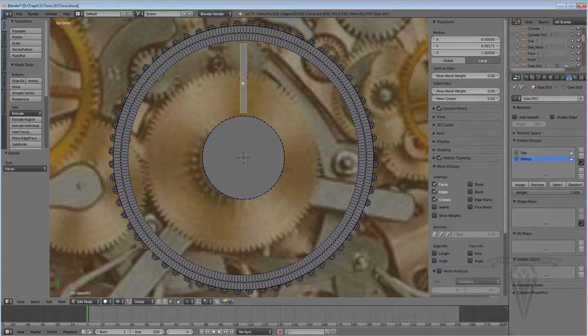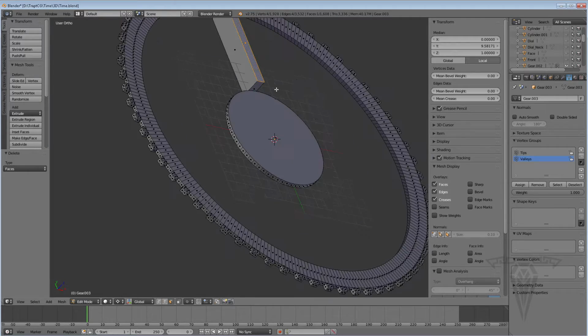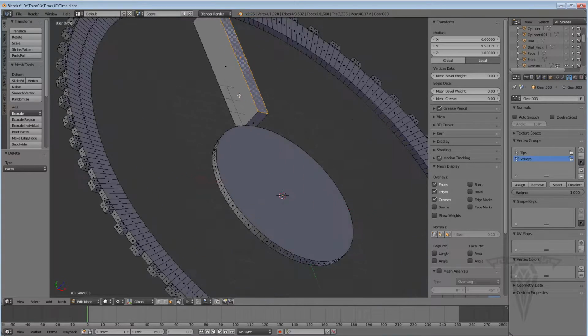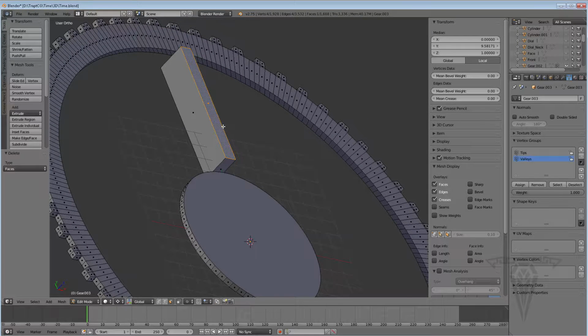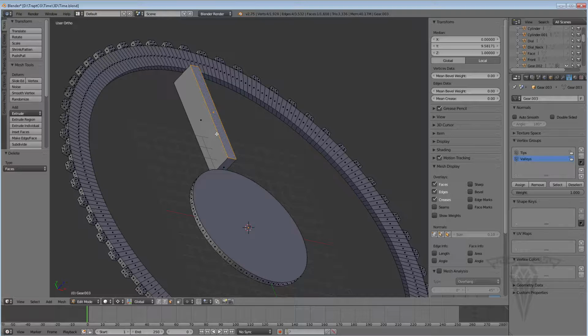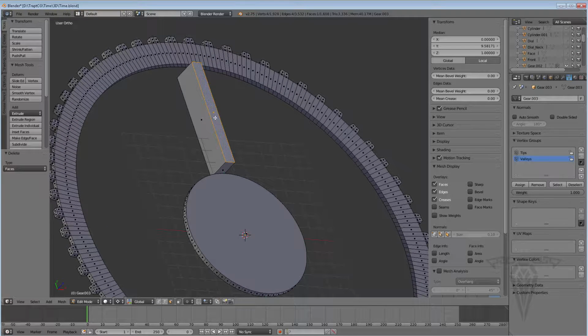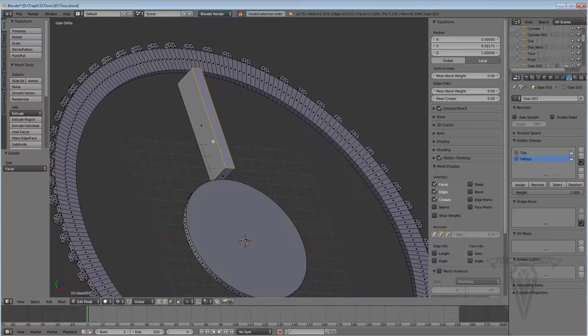Now, if I rotate around this, you can see here when I clicked on it, it just selected the top face. I need to select the whole thing. And of course, I can try to manually go through and select each face. That would take a little bit of time. The shortcut key, however, like in 3ds Max, there's an element mode, which gives me the ability to select individual elements within an object. Blender has that too. The shortcut key is, if you roll over the object and hit J. Oops, is it J? It's supposed to be J.